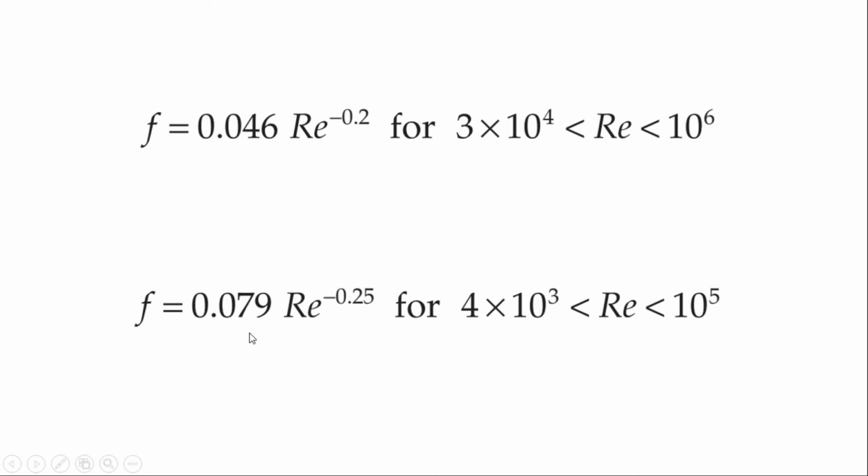No need to memorize any kind of formulas, but you need to understand that for a given situation, a given geometry, or a given scenario, you have to use that formula. So keep in mind that there is no need to memorize any formula. You have to analyze which formula is suitable for a particular scenario, right? For this range, you have to use this formula for the friction factor. After determining the friction factor, you put its value in this formula to get the value of the pressure drop.